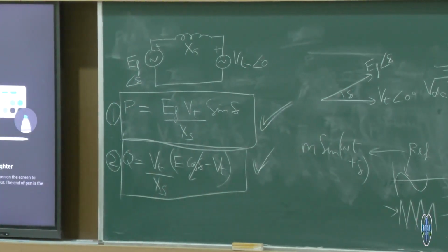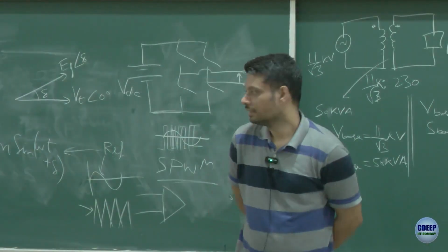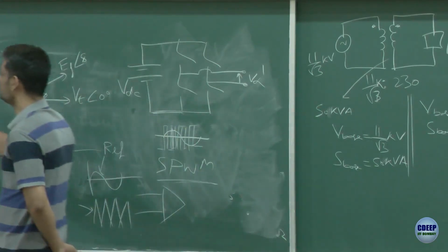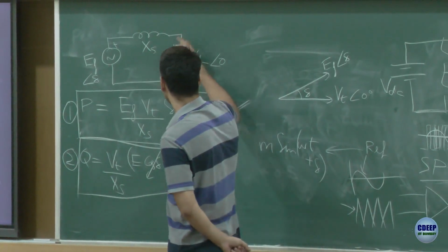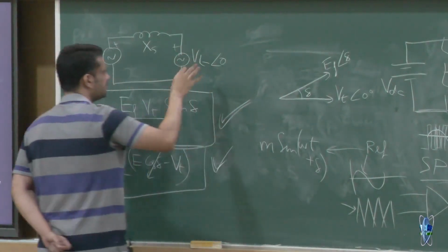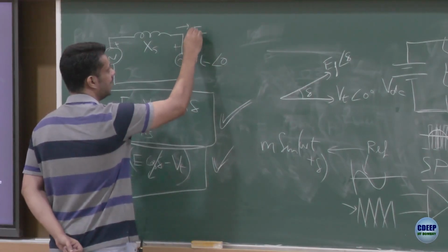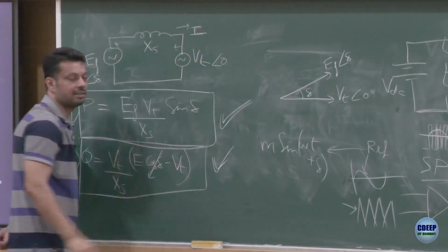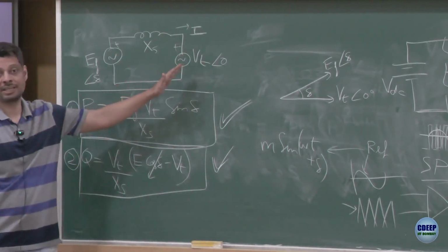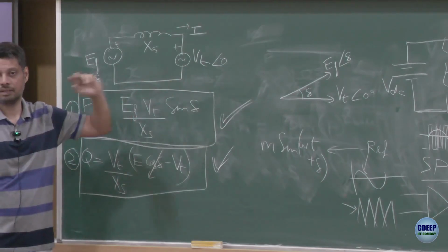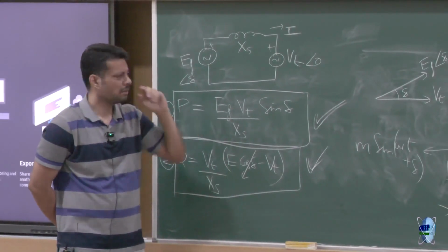Any question, any doubt? Yeah, correct. In this context, there is always an Xs here. What he is saying is, if you have a current here and this current and the voltage Vt make an angle of 0 degrees, that means the current I am supplying to the grid is at unity power factor. In that case, you are saying that you cannot transfer any real power. Why are you saying so?